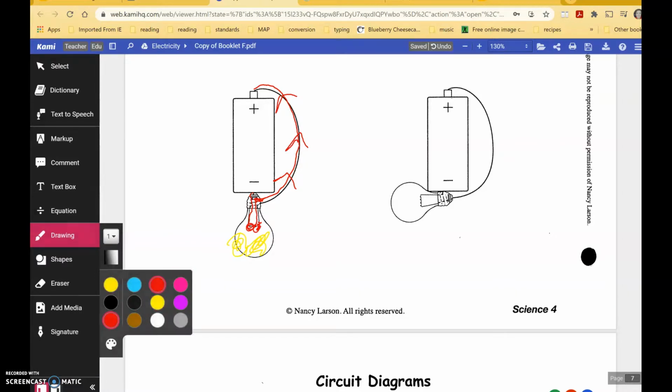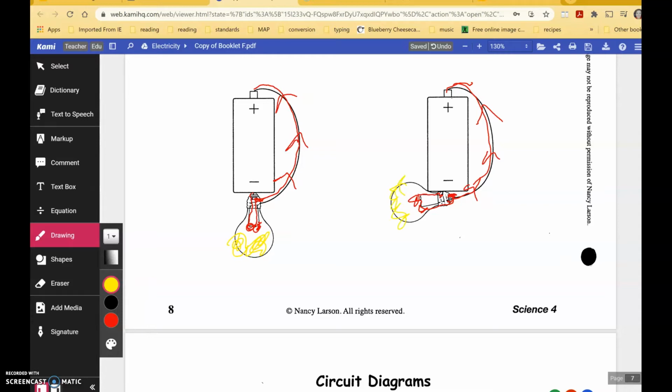And then lastly, we are leaving the positive end, coming here from the negative end on the tip, and the path of flow is like this, up to the positive end of the battery. So by it starting here, it comes up through the lead wires, through the filament, back down, and out that way in order to give us light. Please make sure you have those marked.